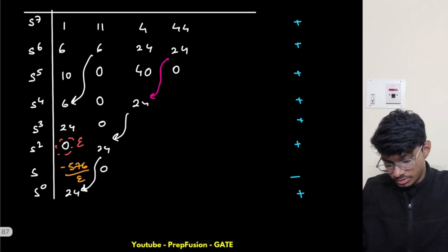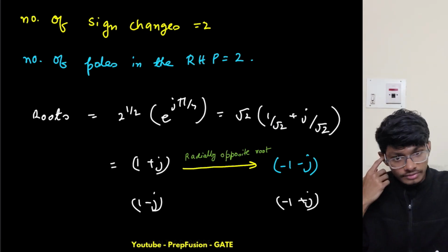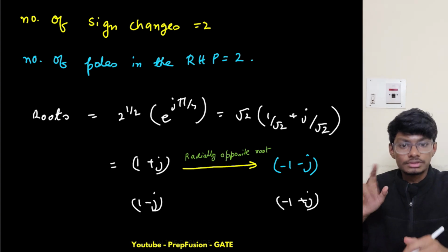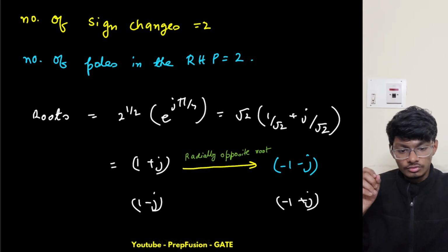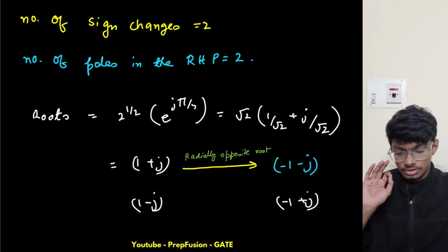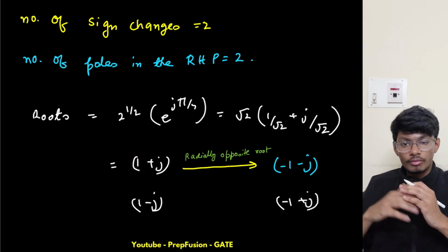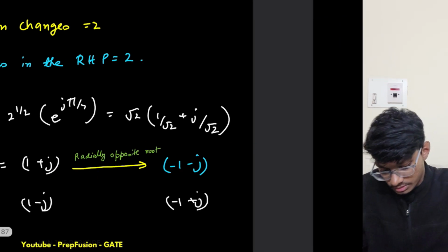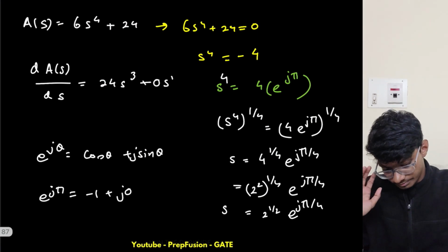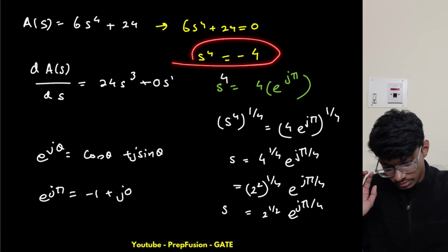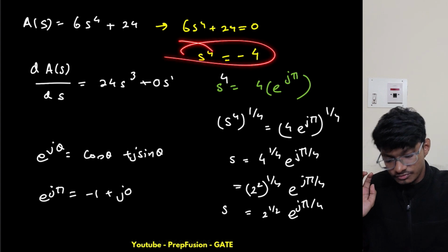Okay, can I find the other 3 poles? So I have how many poles left? I have other 3 poles left. Can I find my other 3 poles? Let's see. Again what we'll do is use the long division method. So I got my 4 poles. Now I will write the factors. So what is the factor? The factor is this one, s square plus 4.